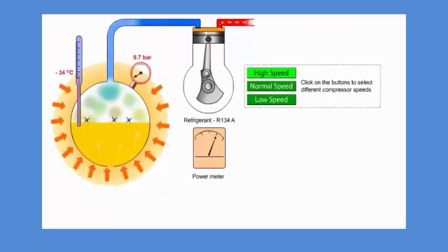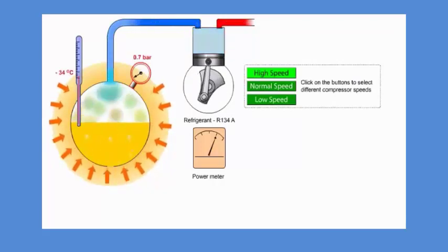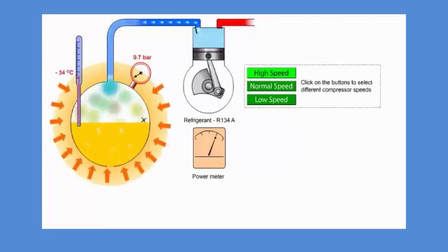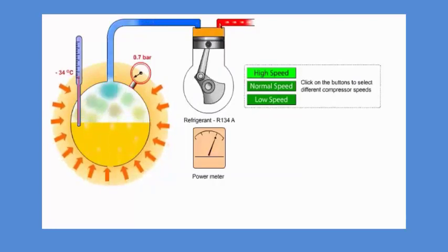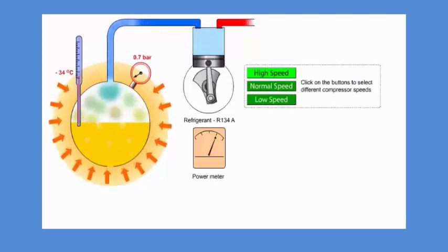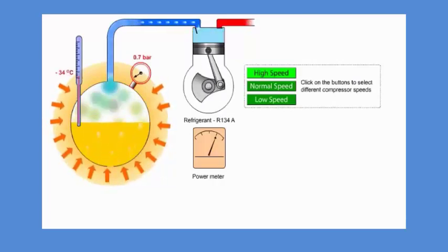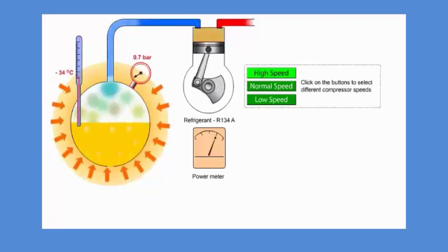This will again cause a more violent evaporation, as you can see, which will continue because the temperature difference between the ambient temperature and the evaporation temperature in the flask is now higher, giving an increase in heat transmission to the flask. A new equilibrium will be established.